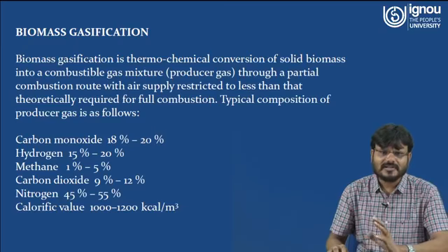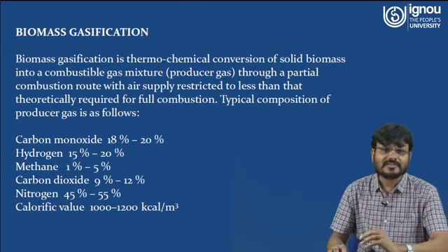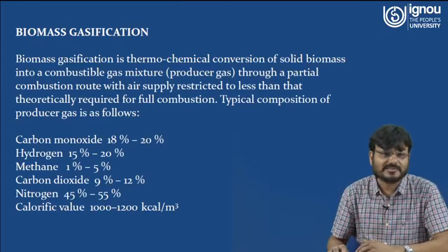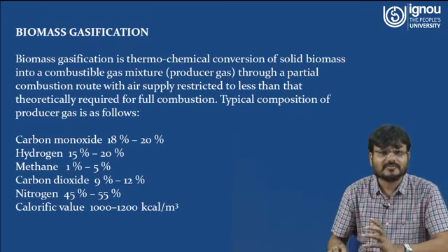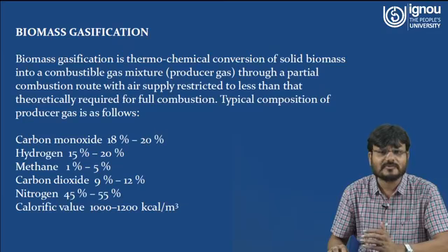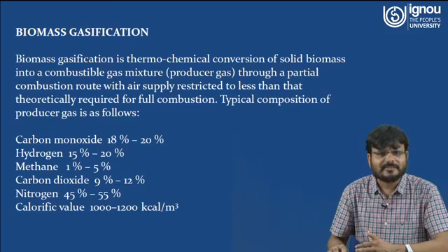Now, the interesting question is, what is biomass gasification? Biomass gasification is basically the thermochemical conversion of solid biomass into a combustible gas mixture, which is also called producer gas, through a partial combustion route with air supply restricted to less than that theoretically required for full combustion.